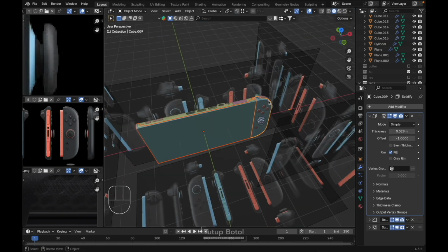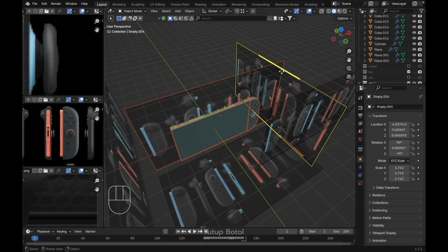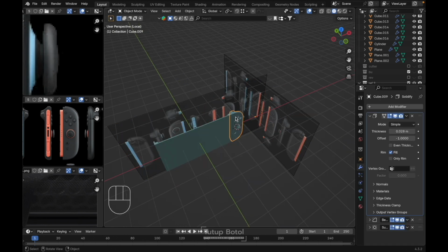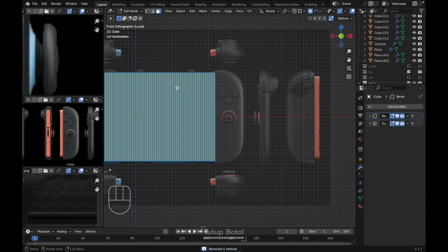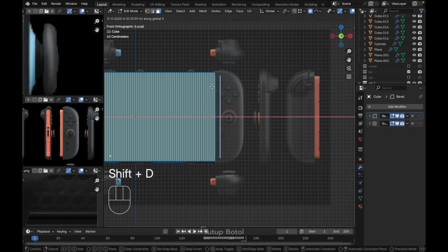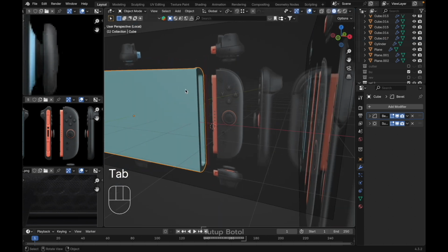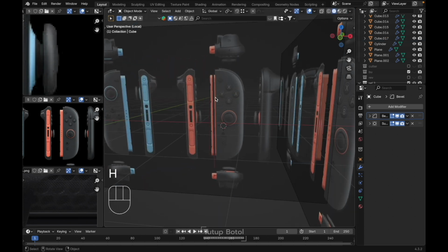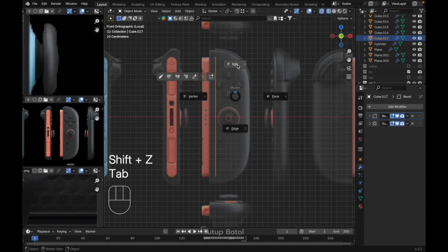Next, for this part, let's only select the object we need. Select two of this one, and this, that's all. Then press slash. Let's hide this one first. Select this one, select this face, Shift D, duplicate it, then X, put it somewhere around here, press P, selection, back to the object mode, select this one and hide this, select this object, Alt Z, tab to edit mode,